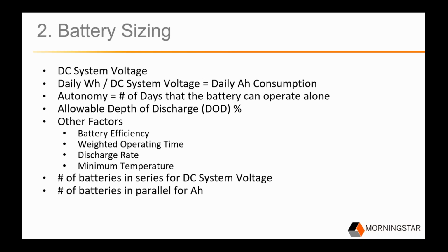The battery size will need to meet the system voltage and amp hour requirements for the loads. The nominal battery voltage depends on the voltage requirements of the loads. The controller selection and string sizing options will depend on whether it's a 12, 24, or 48 volt battery system. You can convert the daily watt-hour load requirements to daily amp-hour requirements of the battery.